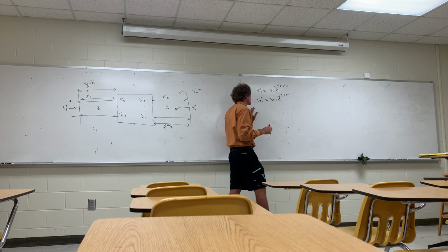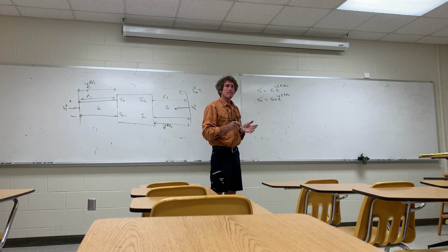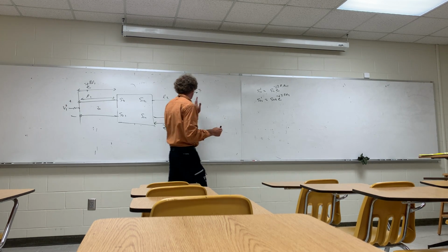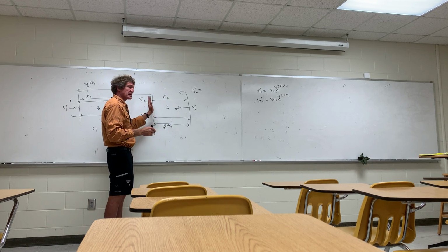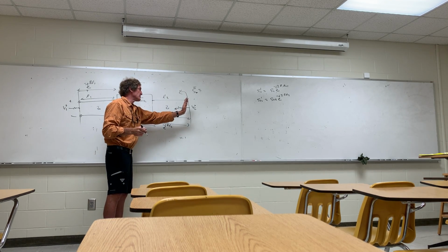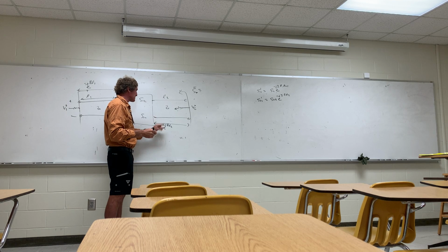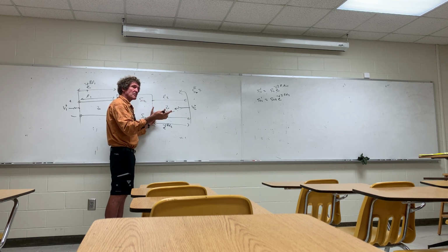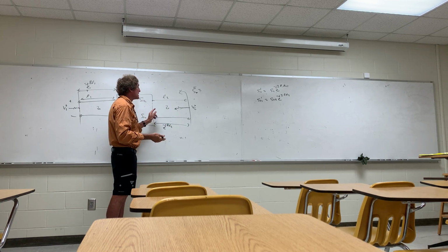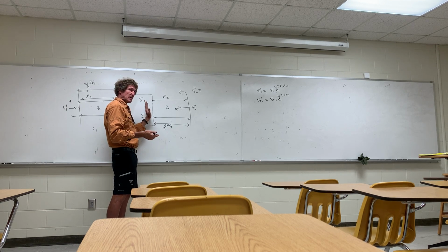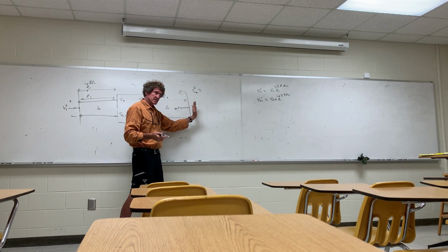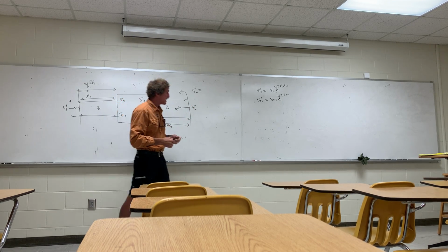So that would be for the reflection coefficients in a matched system, we're assuming. And the two's because it comes back. Yeah, it goes down with this much phase change, right? Then you hit here, so V2 plus is coming down, gets this much phase change before it hits. Now the reflected field is going to be that times S22, right? And then that has another phase, so the total is twice that.